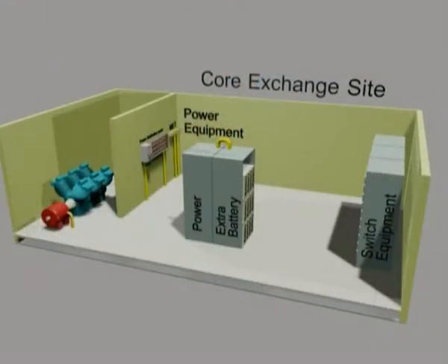So if the AC mains should go down, a backup that can feed the telecommunication equipment with DC for a short time, let's say a couple of hours, would be needed. The batteries provide the DC backup during the time when the main supply isn't supplying the rectifiers with AC or until the standby diesel generators have started up.